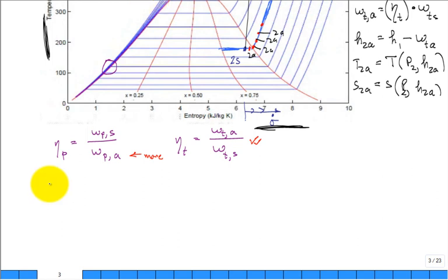And so now you think, okay, well, what's the equation for the isentropic work? There's two ways of doing it. You can do it just like the turbine. Maybe I should use different state numbers. What state number should I start at and then end at? Should I go 1 is the inlet and 2 is the exit, or is that too confusing? Is that okay? So 1 is the inlet to the pump, and 2 is the exit of the pump, which will be right there on a TS diagram at a higher pressure. So it'll be, and I'm going to talk about the positive work, enthalpy 2 isentropic minus enthalpy 1.